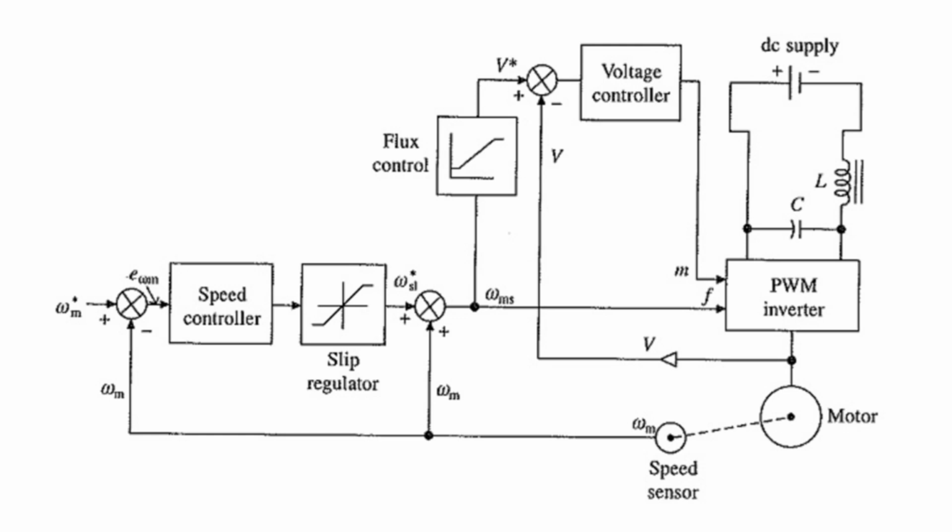So what are the benefits of the inner current control loop? The major benefit is we can limit the converter current. First point, the converter current as well as the motor current, or the motor torque Tm, must be kept below a safe limit. That is the major advantage of the inner current loop. We can limit the converter current as well as the motor current, or you can say the motor torque should be kept below a safe limit.